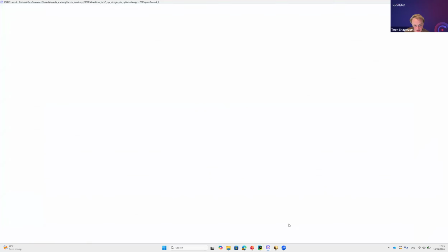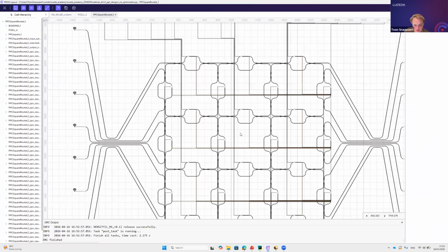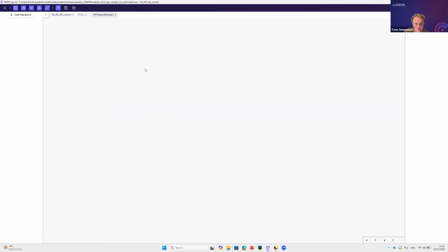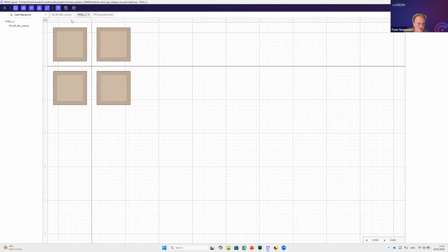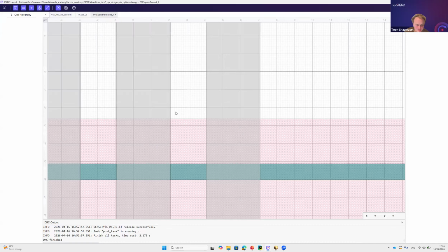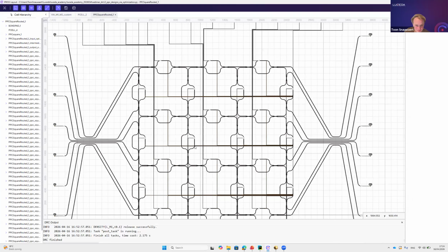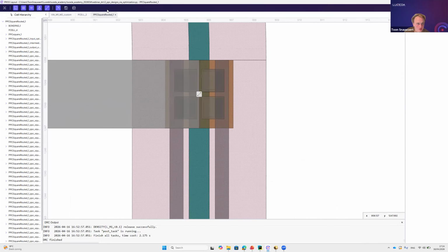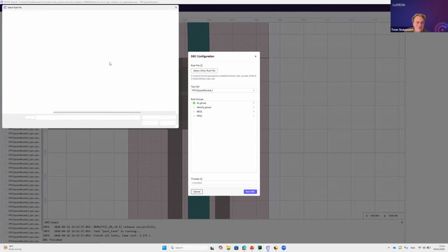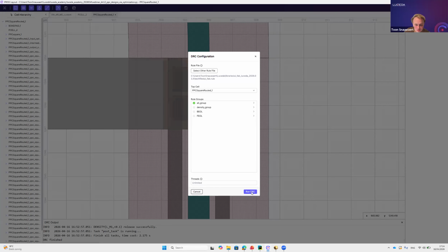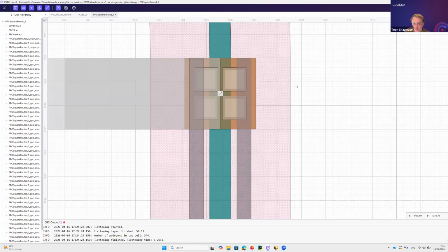Running this code, I get the following circuit with this custom via that I've created, with now 1 micrometer width and length. That is put into this via array. That is put into this circuit. Running DRC should now resolve the error, the violation about the metal 2 layer.